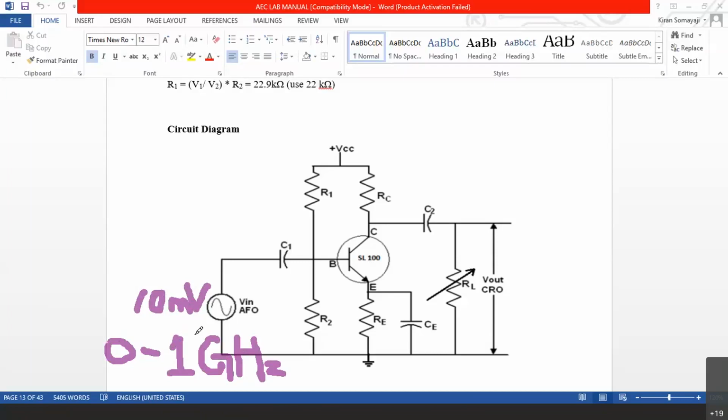I have already told you the usage of semilog sheet in the theory class, right? In module 3, we discussed Bode plot, and I discussed the semilog graph sheet. Now we are going to use the semilog graph sheet in the lab class. That is why from 100, 200, 300 up to 1 kilo, 1000, from 2000, 3000 up to 10,000. That way you are going to keep on increasing the frequency, keeping the input voltage constant.